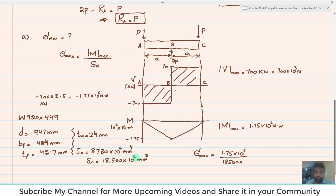This is in millimeter, so if you convert it into meter, it will be 10 raised to power minus 9, and it will give you 94.59 megapascal. So sigma max will be equal to 94.6 megapascal. Now this was the first part of question 8.3. This is the answer.